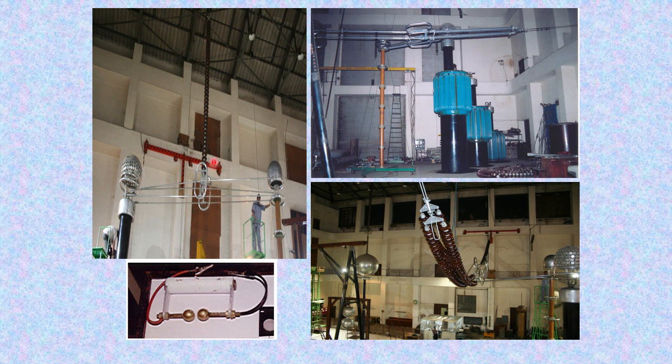We can see here the suspension string undergoing the voltage distribution test. The string is connected in a similar fashion as in the field. This is a laboratory simulation with the corona control ring. The number of insulators, say in 765 kV, we have 35 insulators in place, so the arrangement is similar to the field. This is for I suspension. Similarly, we have one for a double tension, and this is for the quadruple tension.